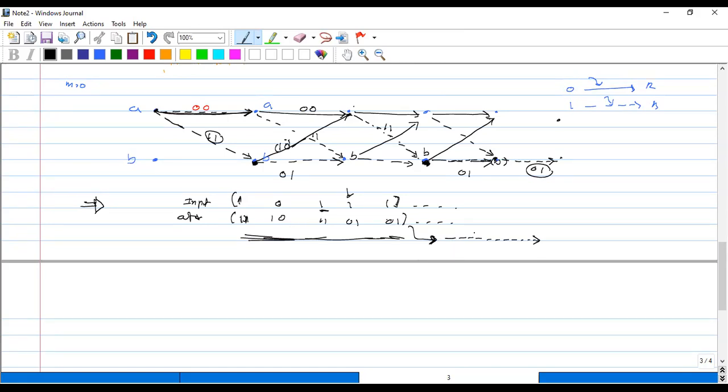If you want to transmit wirelessly, you have to modulate it. If you want to transmit by cable, you do not need to modulate. You can use a line coder to convert these bits into a voltage and just send.